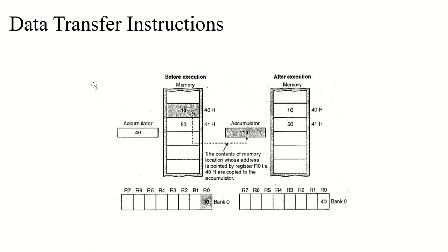And I will make you understand by example as well. It is only a single byte instruction and includes only one cycle, and always remember we have @ and Ri. So this is register indirect addressing mode. Okay, @ stands for indirect, and we are involving registers in it, so it is register indirect addressing mode, and no other register or flags is affected here.